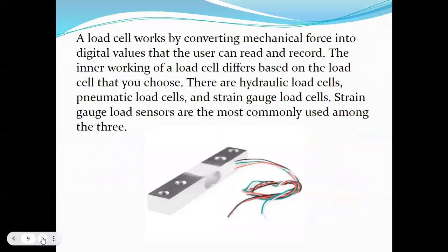A load cell works by converting mechanical force into digital values that the user can read and record. The inner working of a load cell differs based on the load cell that you choose. There are hydraulic load cells, pneumatic load cells, strain gauge load cells. Strain gauge load cells are the most commonly used sensor in the market and in the industry.